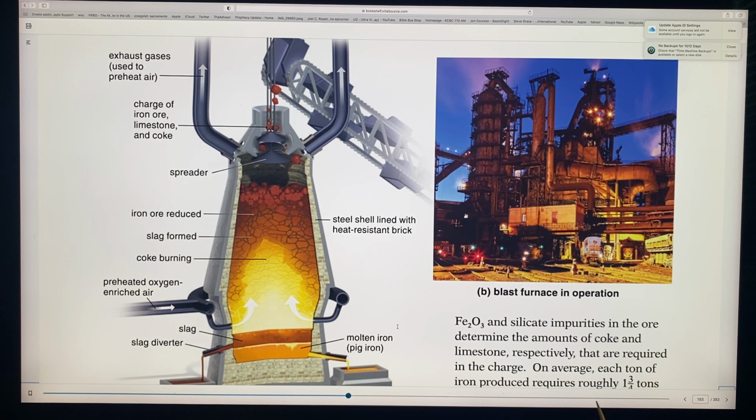It consisted of a vertical heat-resistant column that was filled with the ore and fuel, where the chemical reactions took place, and they would force air into this furnace at pressure. The pressure nozzles at the bottom make a very hot flame, and the liquid iron would collect at the bottom. We have pig iron at the bottom and collect there.